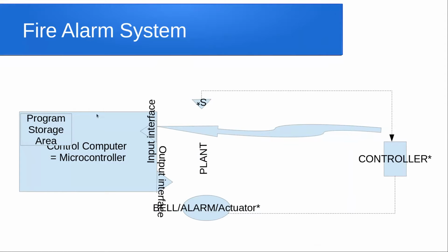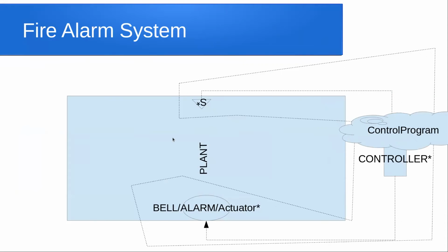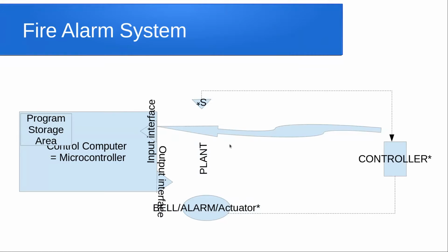So this is your microcontroller board, which has an input interface and an output interface. This arrow that is going in here, we are zooming into that. Whatever is the box in here, we are zooming into that, and accordingly we are seeing it. So the input from the sensor is going to a kind of analog to digital converter. Then it gets read by the program being executed by the microcontroller, and then we also have an output interface. After this program has processed the inputs, it computes the outputs which are driven onto the actuators, right? This output corresponds to this point in here.